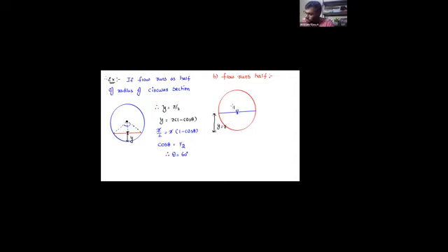And what is the top width, please? See, remember, flow runs half means that's going to be a semicircle, right? So what is the top width over here? The top width is nothing but the diameter of the circular section, 2r. Or in other words, what is the angle made by a semicircle? 180 degrees. Total circle 360 degrees, semicircle is going to be 180 degrees.